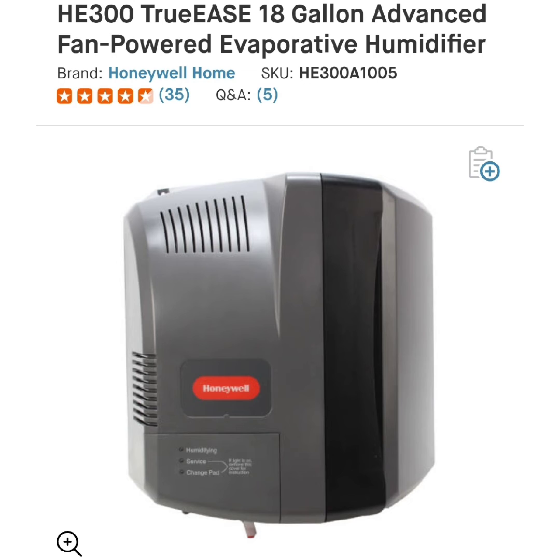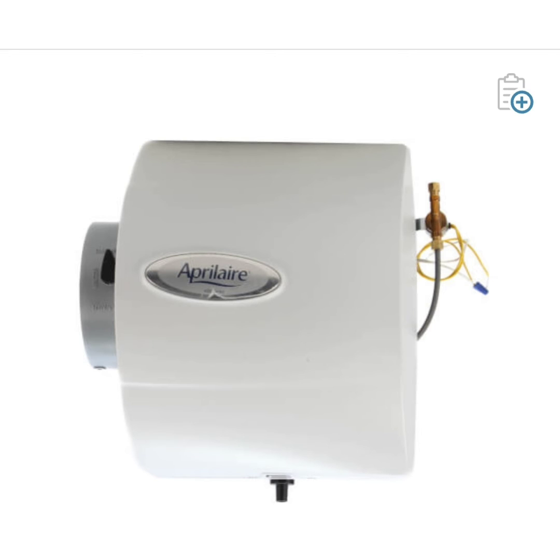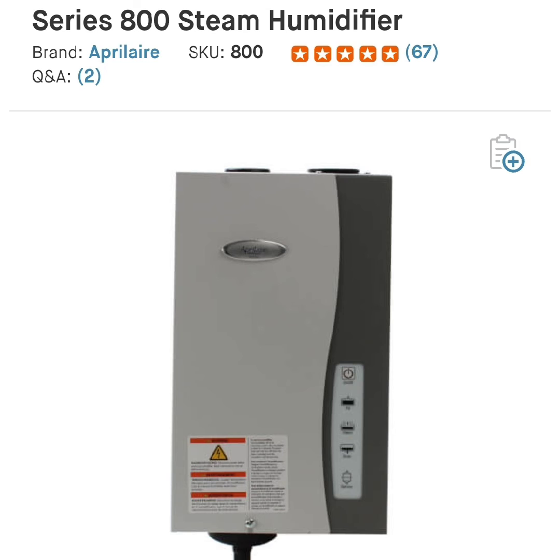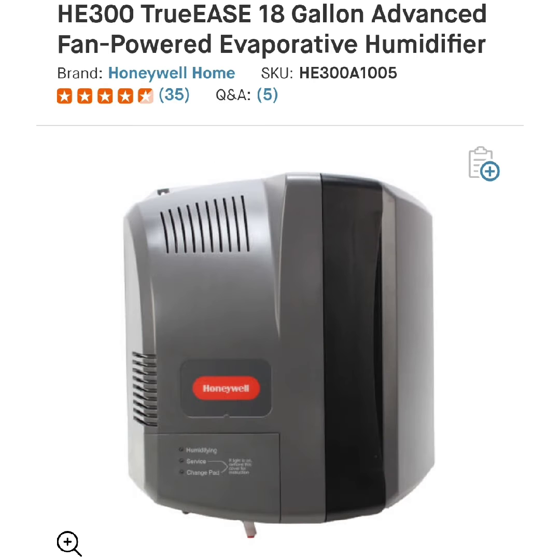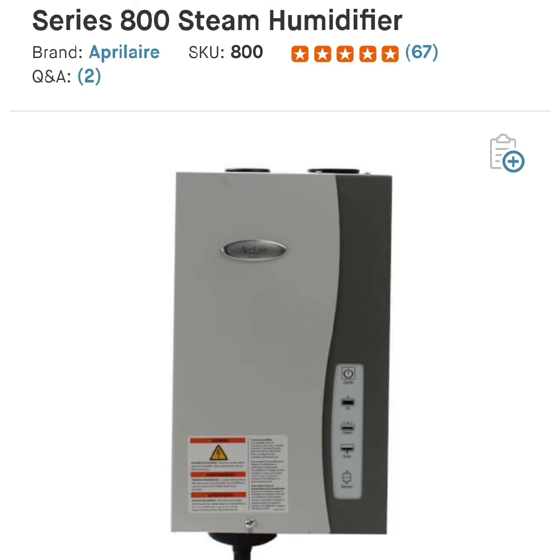So these other economy model humidifiers just aren't going to cut it anymore. No, we're going to have to step up to a higher capacity humidifier. That's why I prefer a steam humidifier. It has the capacity to handle a dry building, and it doesn't add to the heating load either. Something else to consider is that evaporative style humidifiers, normally the more economical ones that don't turn the water into steam and don't add any heat to the water, actually require a little bit more heating capacity out of your heating system. That's called humidification heating load in Manual J, because as that water in the humidifier evaporates, it actually cools the air a little bit, and your heating system has to overcome that.